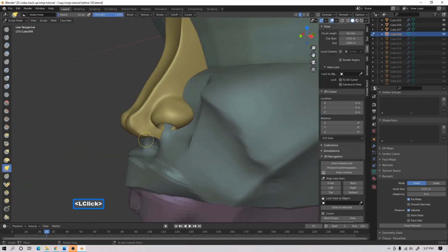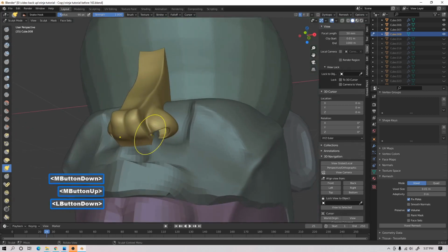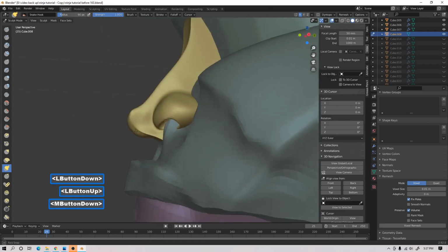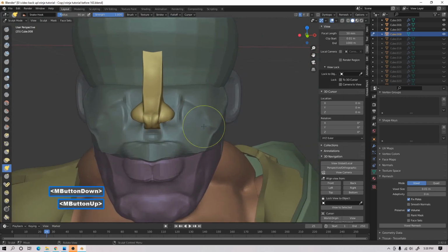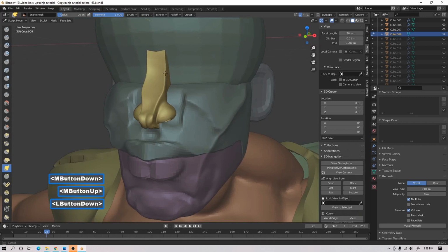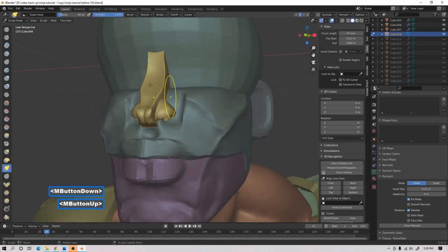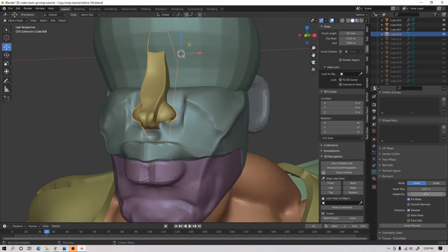We'll go back to the snake hook. I'm going to lower the geometry on this. I can do that by putting in 0.008, selecting voxel remesh.